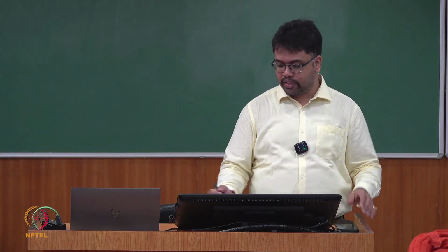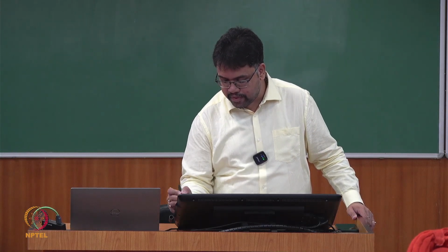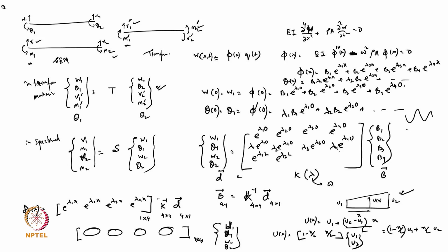Now, for example, in finite element you have to refine your mesh to capture that, because if your vibrating structure is like that, you cannot take a mesh size like this. That's impossible, because you are already assuming that your variation is linear. So this single element can give only this type of result. It cannot give this internal fluctuation, because there is no inbuilt thing inside to capture that.